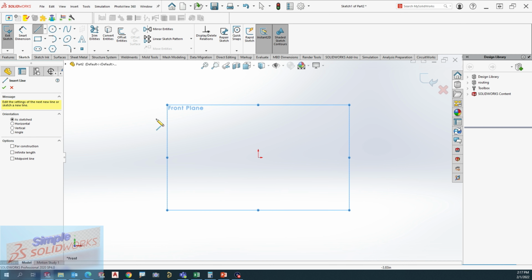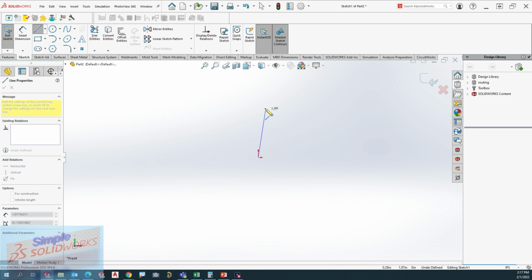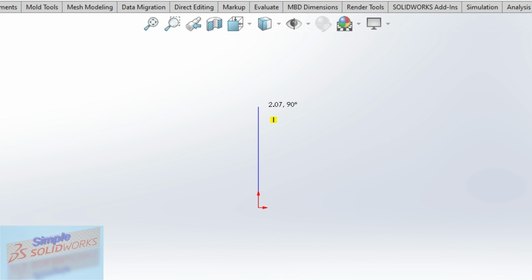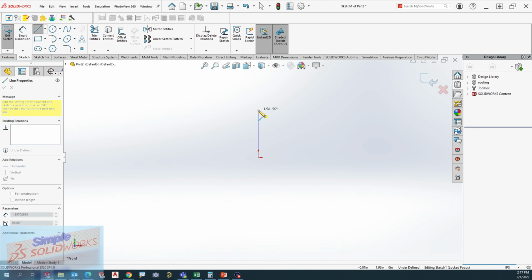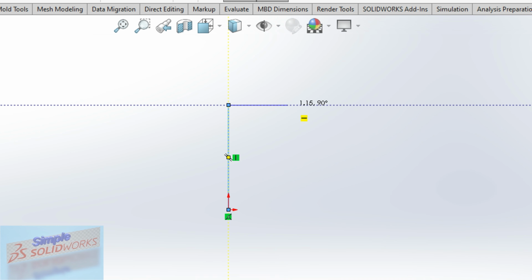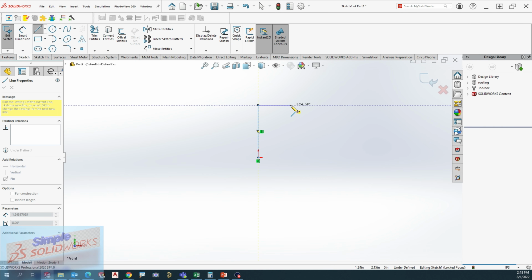You just click on it, it's going to tell you where you want to place it, and you start just drawing. If you notice, if it becomes yellow like it is now, that little yellow line that you see there, that means that it's always straight. It's going straight up on the vertical. And if you go across, it also does that same concept, and it shows you that it's going across horizontal perfectly. So this is very basic.